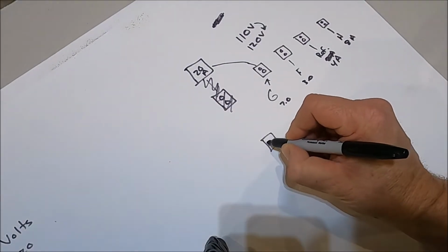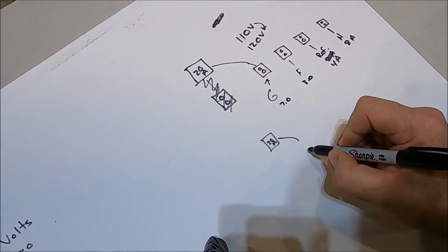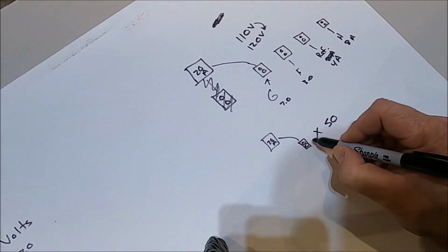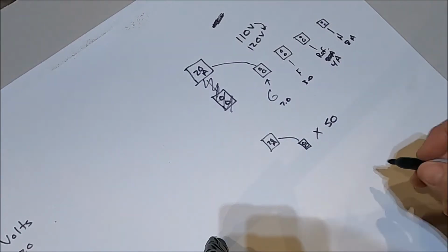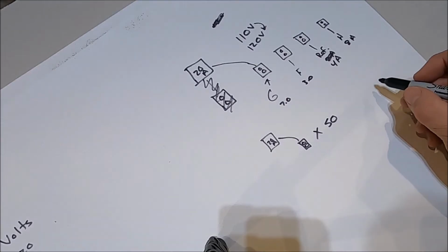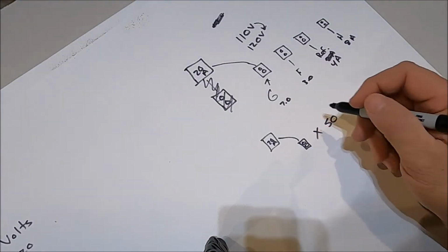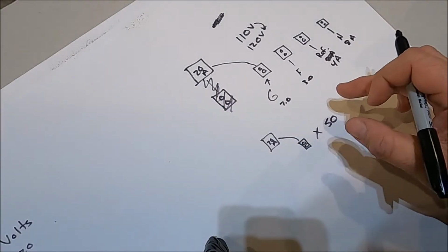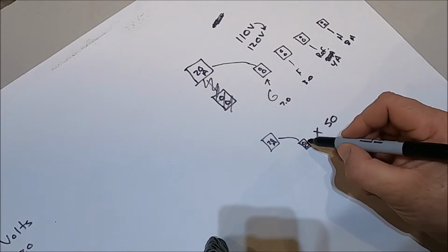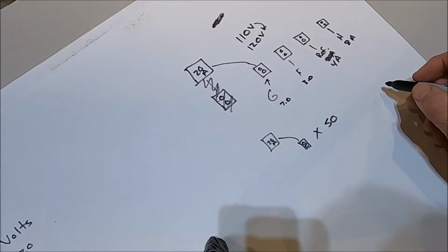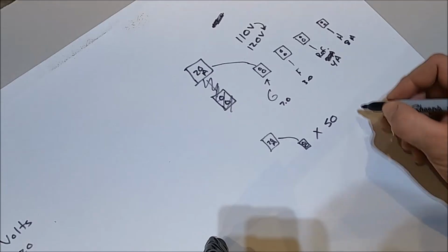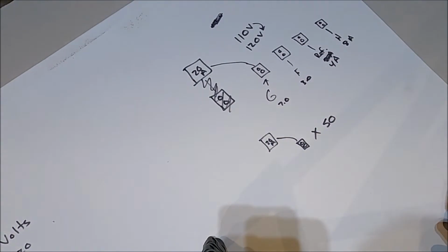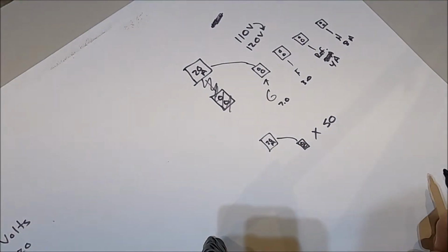But there's also something else. Say you have a 20 amp breaker, and let's just say you have 50 outlets on here. But let's just say you're not using them all. So say you just want to have outlets in different places so you have access at different times, but you're not going to be using over the 20 amps, then you're fine. You can have as many outlets on here as you want. And as long as you're only using a couple at a time and you don't go over the 80% amperage of the 20 amp circuit, the 20 amp breaker, you'll be fine.